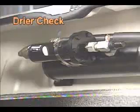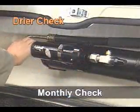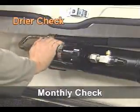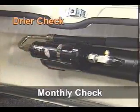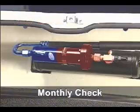When the refrigerant line is polluted, the dryer may be clogged. Dryer clogging can be checked by the temperature difference between the inlet and outlet pipes by hand. The temperature should be the same. If you can feel the temperature difference, replace the dryer. The dryer is a monthly check item.